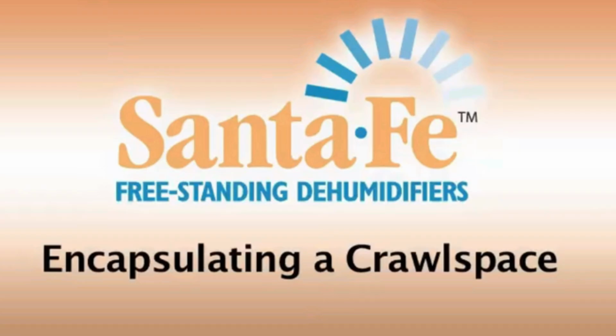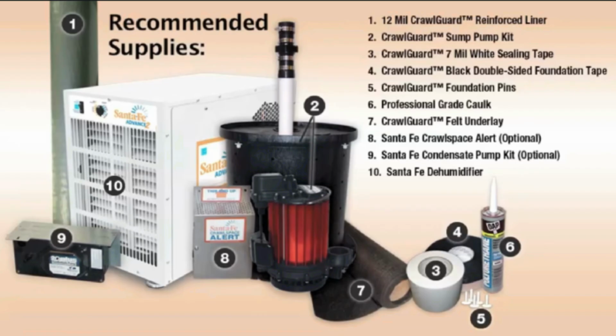In the next portion of our course, we are going to use materials provided by Santa Fe dehumidifiers on encapsulating a crawl space. On this slide, you are seeing a list of recommended supplies. Our first supply would be a 12 mil CrawlGuard reinforced liner. Our second supply is a CrawlGuard sump pump kit.